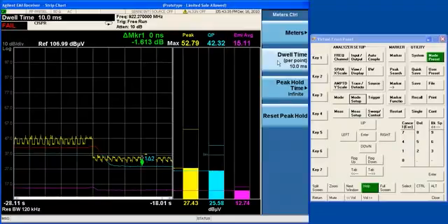So let's, for example, say that you have a 1 RPM turntable. That means you're doing 6 degrees per second. So I would like to get more than 6 points per second, say, to make sure that every degree of rotation is captured by at least 1 point. So a 10 millisecond dwell time gives me 100 points per second. So that's plenty fast enough to make sure I have 1 point per degree. In fact, I'll have about 16 points per degree.